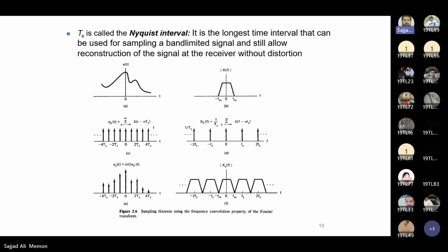At every different frequency we have a rectangular signal, but that's not an ideal rectangular signal. So this is what we have got after the sampling. But if we follow the Nyquist criterion, then you can recreate the actual analog signal from the sampled signal that looks like this.